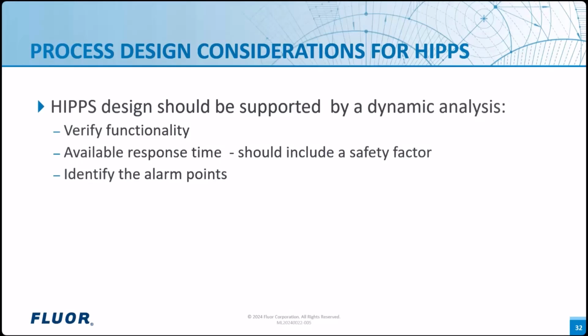The alarm points might be adjusted to provide more response time, but consideration of the operating margin and disturbances is important. Note that a rupture disc and PSVs tend to react relatively very quickly. It can be a challenge to ensure the HIPPS systems act quickly enough to prevent the overpressure. The response time of all of the components in the HIPPS must be considered.